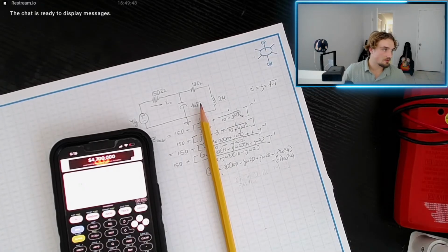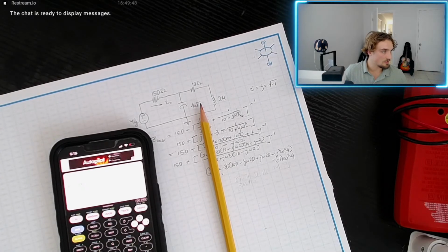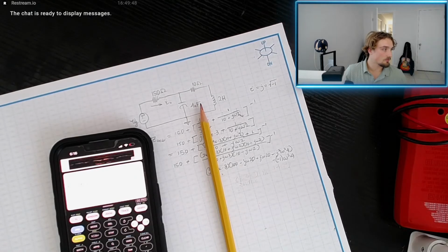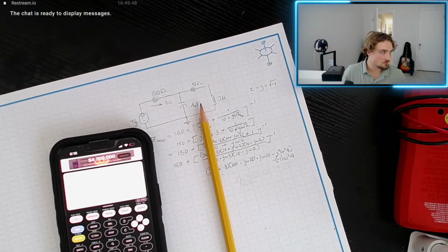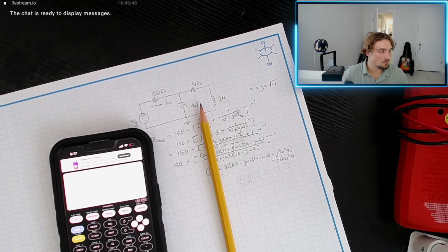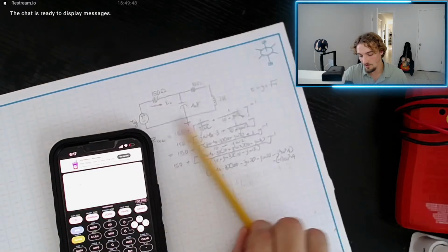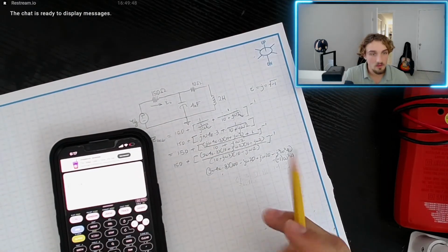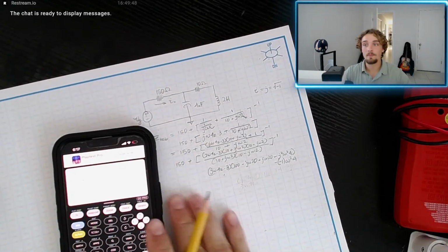Alright, no, it's not mathematically necessary to use polar coordinates, but it's highly recommended to avoid tedious algebra. You can perform these calculations in rectangular form, but the process is much slower and more prone to errors. You multiply by the complex conjugate of the denominator to eliminate the j term from the bottom. This takes several steps. Polar form multiplication, multiplying the magnitudes and adding the angles, is much simpler. I get it. But I've already gone this far with this method, so let's try to continue, I guess. Alright.